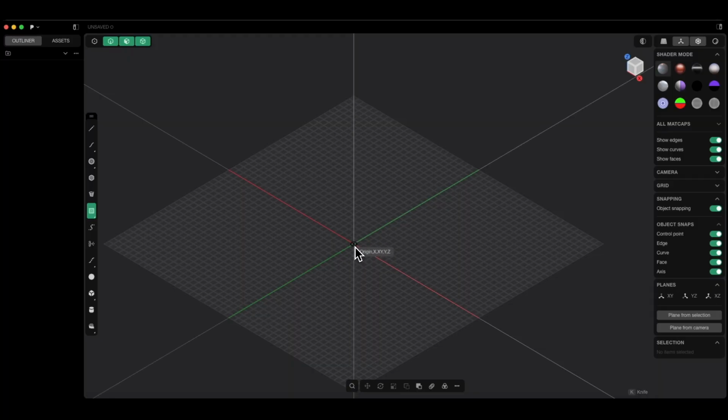To do this, we hover the cursor over this point and click the left mouse button. Now we can draw the rectangle, and I would like to draw this rectangle with specific dimensions, for example 200 by 50 millimeters. We can try to do this by dragging the cursor. However, as you can see, even though the dimensions are displayed, it's difficult to precisely catch those values, but